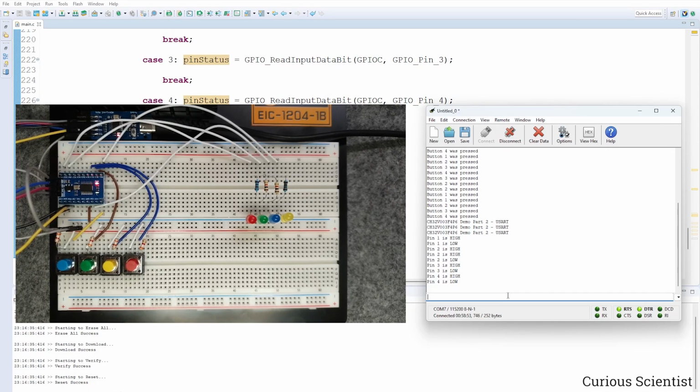And of course, it's not really probable that you would want to do this, like read the buttons so manually or so mechanically. But it can happen that you want to, let's say, read the status of a certain GPIO port like this, because it is modified by another device, an external sensor or a limit switch or whatever.